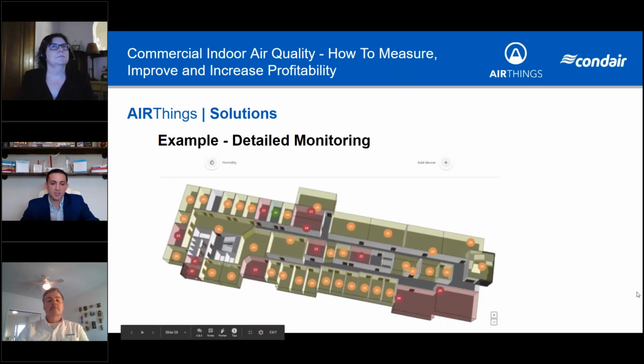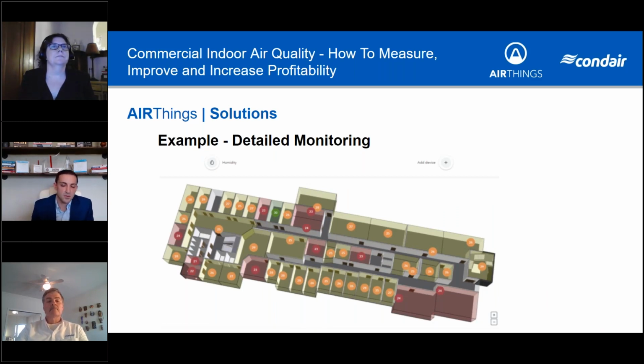And here we go. So this is again a small portion of what we have in our dashboard. This is actually humidification. I think it's one of the most critical parameters we can look at, both from our machine life expectancy and occupant health, and it's a relatively easy fix, and the benefits are endless. So this is an example. We can actually upload schematics into the building management system, where it's a little cleaner. It's not an interactive demo, but you'd be able to click on each one of those sensors and get those parameters and hopefully find out what's going on with that room.